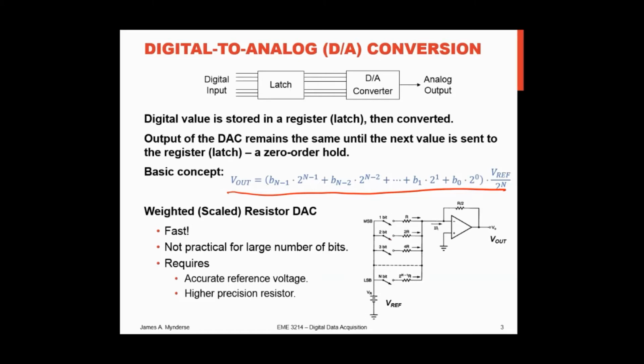So we're taking each one of these bits, multiplying it by a resistor, so that's this term here, the 2 to the n minus 2, or 2 to the n, or 2 to the whatever, multiplying it by the resistor that correlates to that amount, and then the feedback resistor here. And we have essentially a circuit that adds and multiplies all at the same time and gives us the V out according to the equation here.